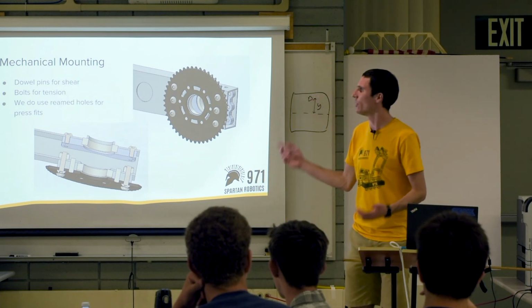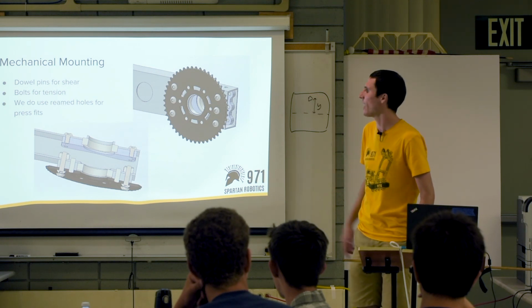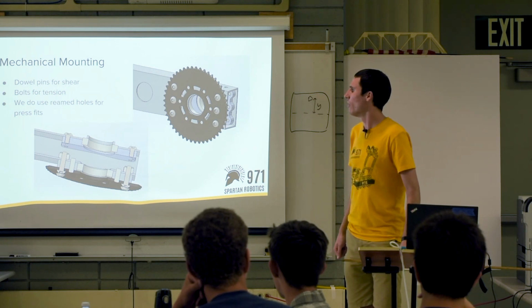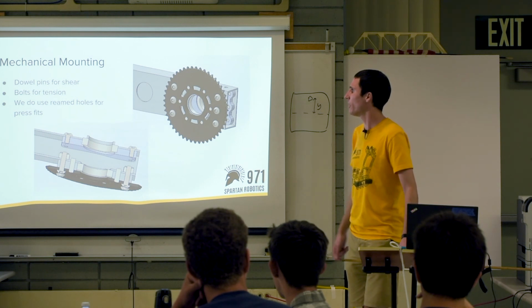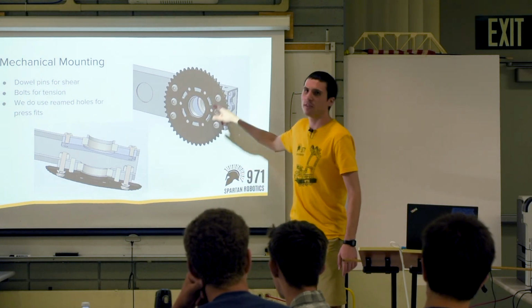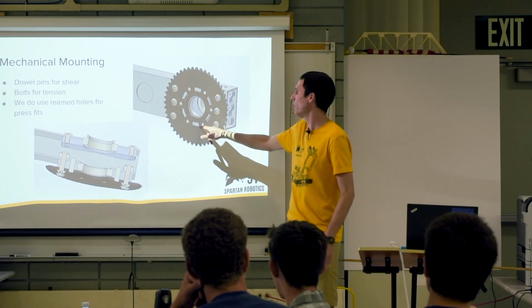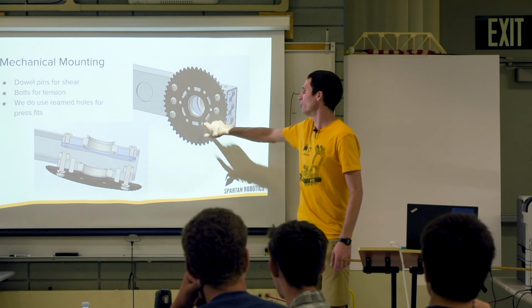So what you do is you drill a hole undersize, and you take a reamer, and it precisely sizes it to the exact fit. So we use a lot of 3/16 dowel pins. It's convenient because if you take the VEX Pro sprockets, they have a bolt pattern here to be used for bolting it on with their Versa key. What we do is we just drill and remount.